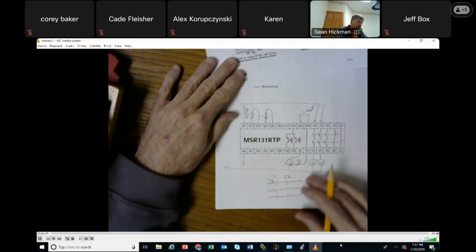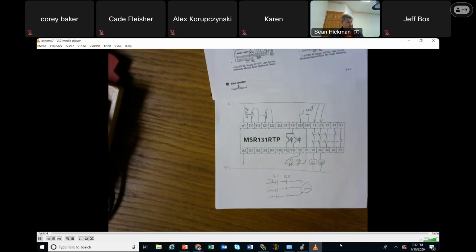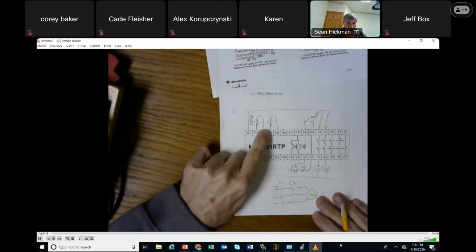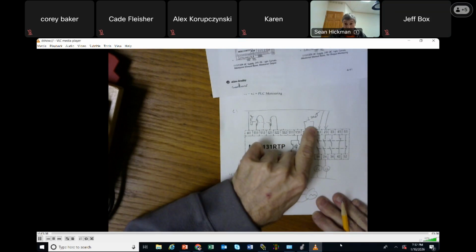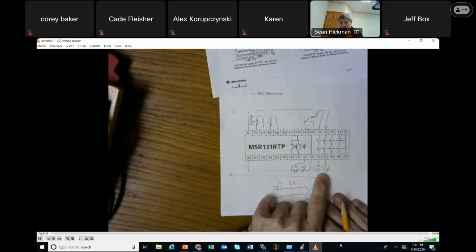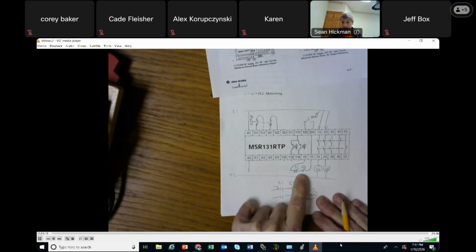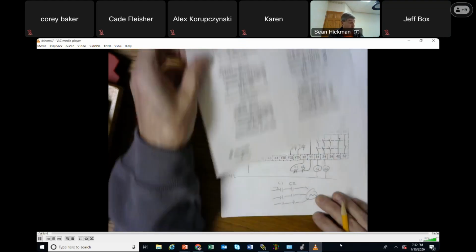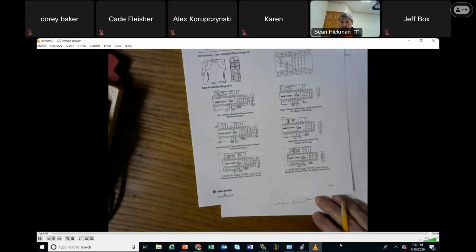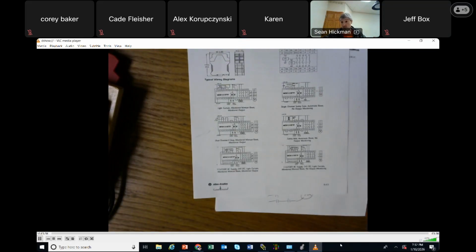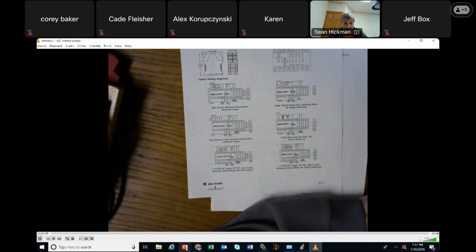Okay, so this is the situation of using a 2-channel E-stop with a manual reset, turning on dual safety contactors, which would be K1, K2 really. The K1, K2 to turn the motor on, and it's monitored. It's monitoring the condition of K1 or contactor 1 and contactor 2. That's what this one here is showing. Okay, so we'll be doing these for a couple of weeks, and they'll get better and better at them.